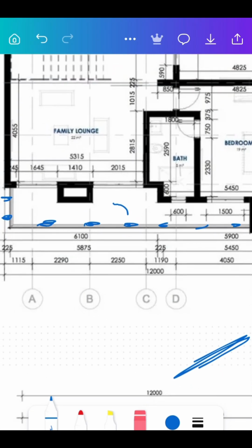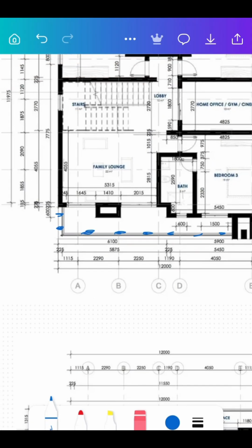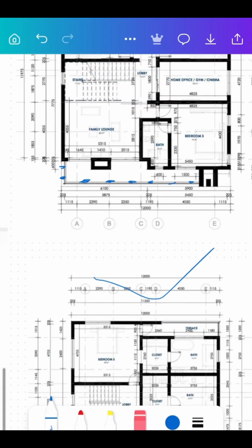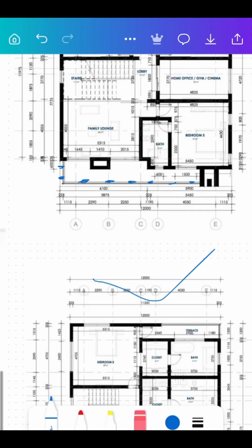Now the thing is, although it is said that you should place your steel bars 120 centimeters away from each other, they need to not pass 120. You can place them at 110 if you want, but you shouldn't exceed 120. If you are putting them at something like 50, the distance from each other is fine, but you're going to use more steel bars, and that's going to cost more in terms of material.